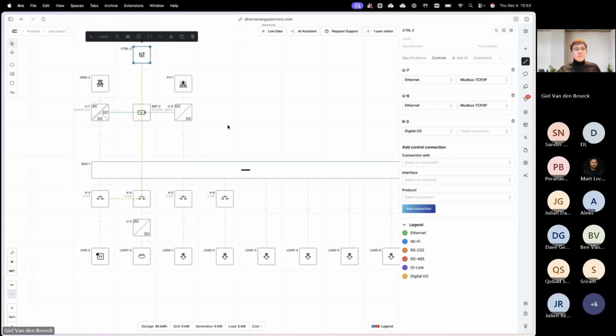Like this. I mean, you get the picture. This controller, we selected a Phoenix Contact controller, a PLC Next AXC F 2152 unit. And actually, anyone that would start developing software to control this system, meaning we want to control the DC bus voltage, we want to control how much solar output we might want to curtail. For instance, we want to control the battery charging in here. Anyone that wants to accomplish that needs to basically today start from scratch with such a controller.